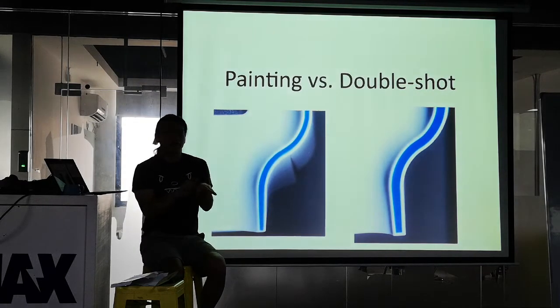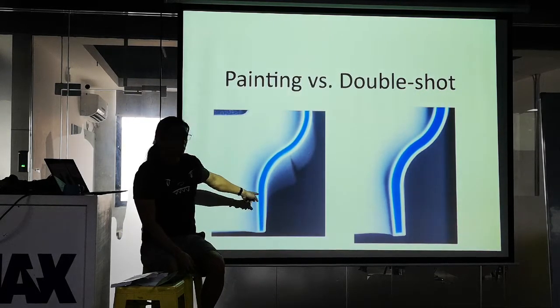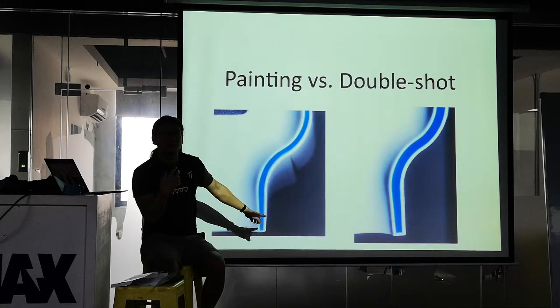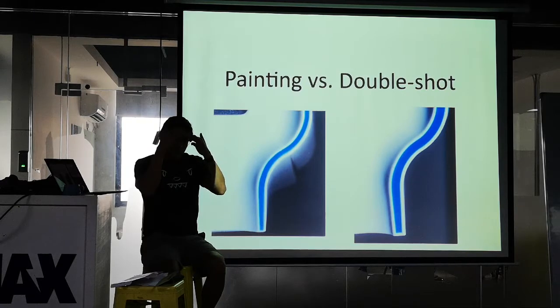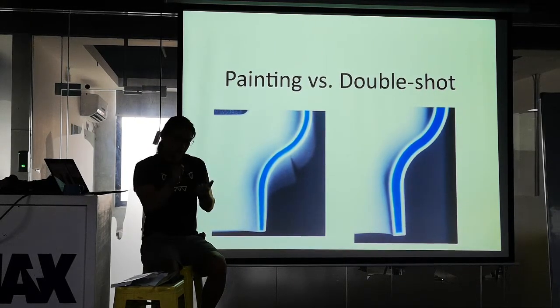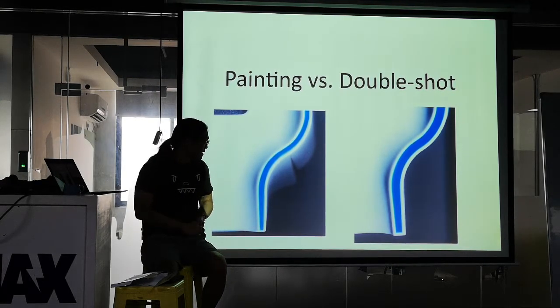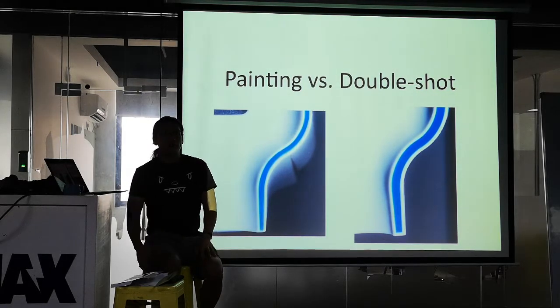So we couldn't get the alignment there with pad printing. We couldn't get there with silk screening. We looked at all types of processes. What we ended up with is the same process they used to put the face on Barbie dolls. So Barbie dolls have eyeballs and eyelashes. There's a lot of fine structures put on her face, and it's all using this sort of metal stencil they put on the face with the jig that aligns it. And they would use spray paint on top of it. So we used essentially the Barbie doll process to put this on.